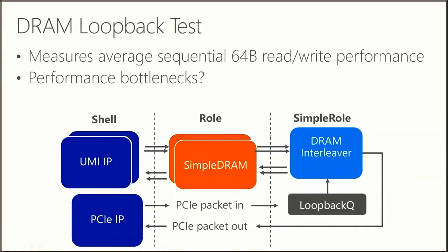Okay, the second sample project is the DRAM loopback test. It is a more complicated variation of the PCIe loopback test. Instead of directly sending data back to the host, it first writes it into the DRAM memory, reads the data back, and then sends it back to the host. It shares the same host program as the PCIe loopback test, but provides lower performance since it is bottlenecked by the DRAM read-write throughput. The project demonstrates how to interface with DRAM and soft registers and provides some useful library modules.